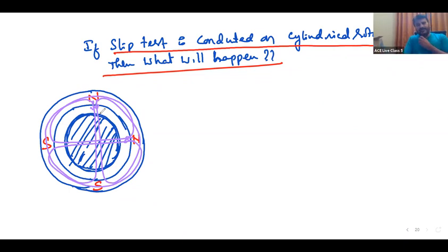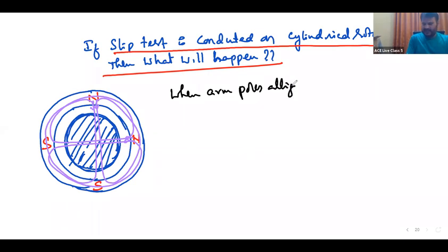Same area everywhere means the ammeter reading and voltmeter reading are constant. No variation you will get. That is, XD is equal to XQ. See what is going to happen when armature poles align with the D axis or the Q axis: the air gap is the same.